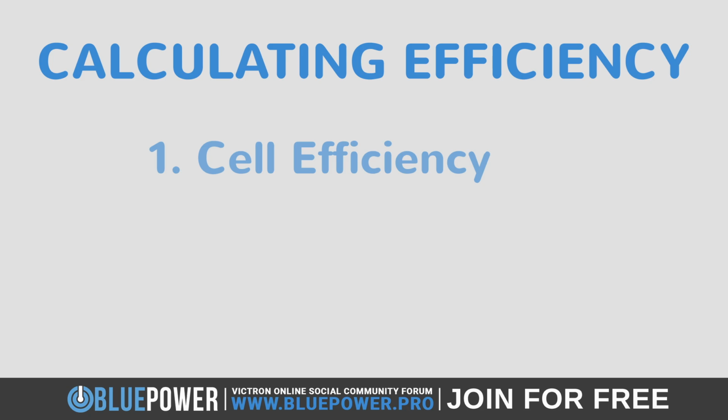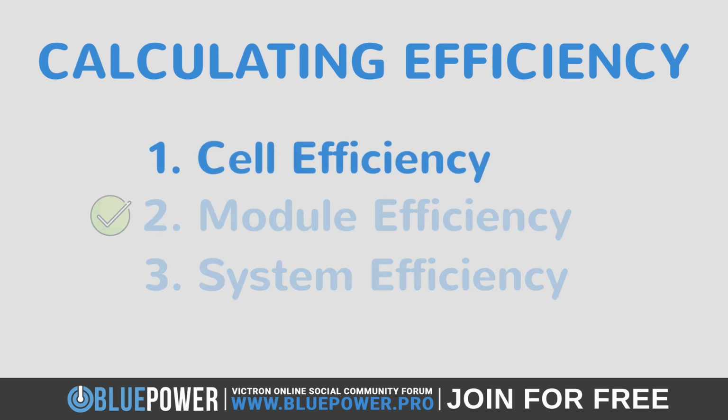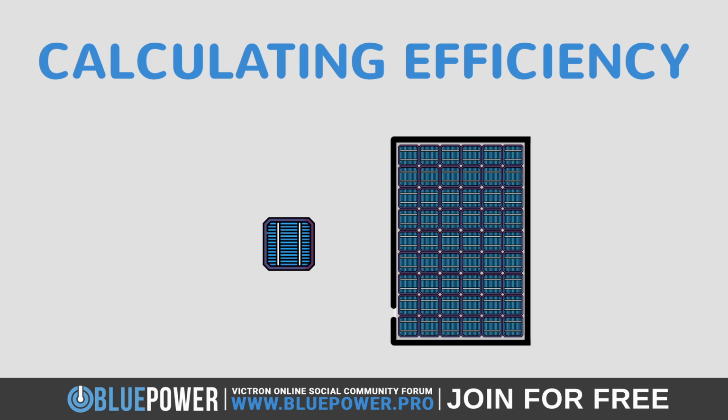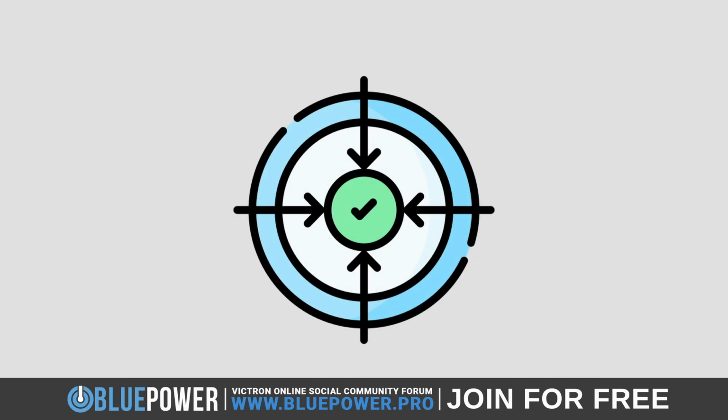Okay, great. So now that we know how to calculate the total module's efficiency, what about the efficiency of each cell, and why would we want to do this? Well, the reason we would like to calculate the cell efficiency instead of the total module is because the module includes the metal frame in its dimensions, which doesn't actually form part of any energy generation. Therefore, by ruling this out, we can get an even more accurate efficiency measurement.